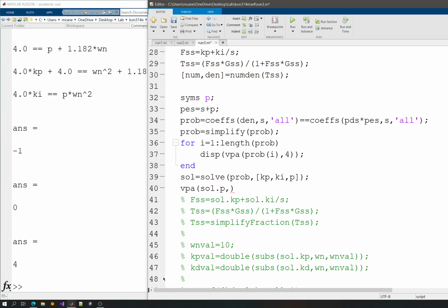Since if you think about it, if I have a third order polynomial, determining the stability needs the Routh-Hurwitz criterion or some other stability checking algorithm. But in this case, since I have assured that the two dominant poles will be on the left-hand side, I'm just looking at the third pole, and by checking if it's a positive or negative value, I can determine the stability. This is much easier than going and looking for a stability test. So keep that in mind.